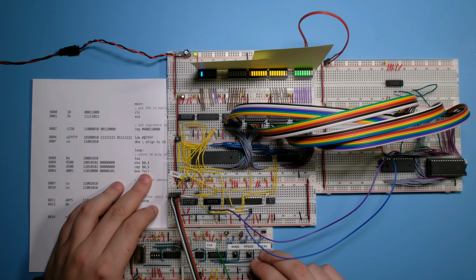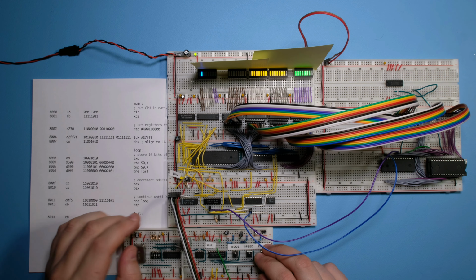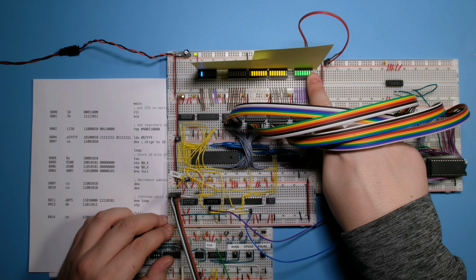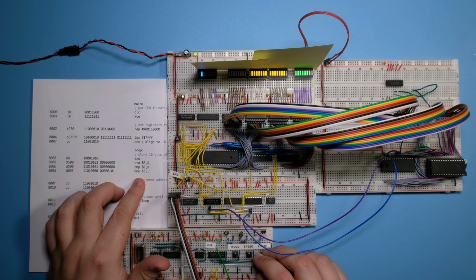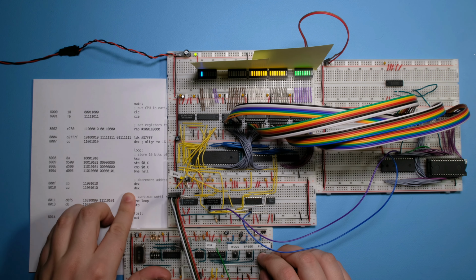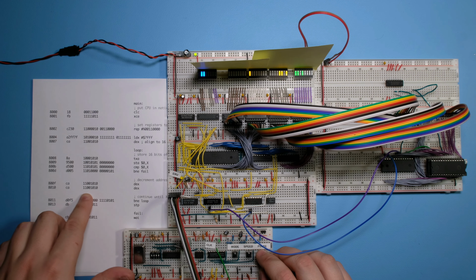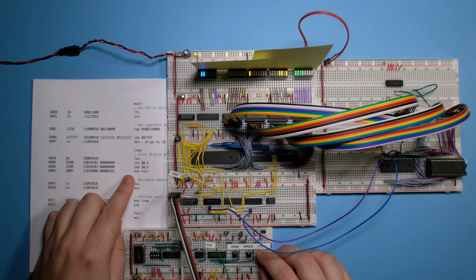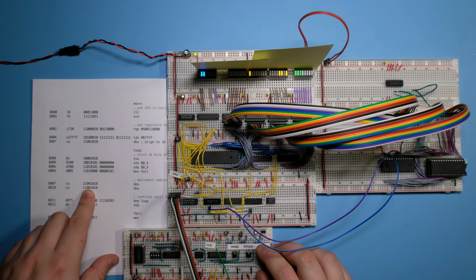And then we should be reading from the address 7FFE, and we should have the same data that we just wrote, which is correct. And so because the data is the same, it's going to continue the loop. And so it's going to go into decrement. And as you can see, we have the decrement instruction. No, sorry, we are loading first the branch not equal. And it's not going to trigger, and so we're going to continue to the decrement.